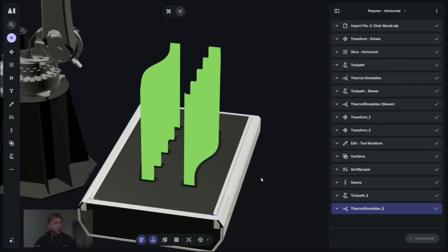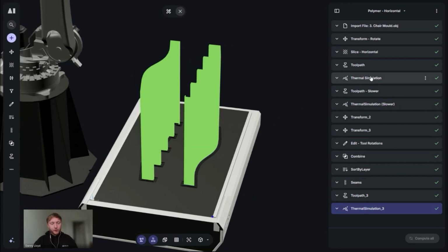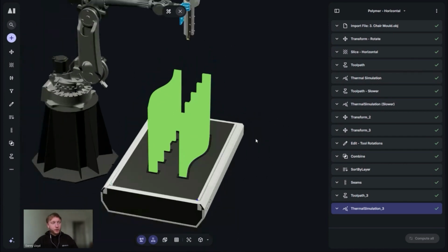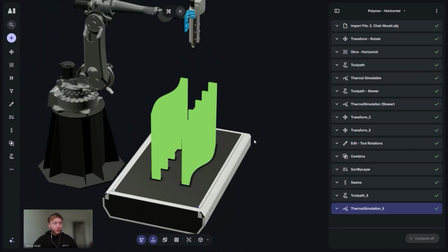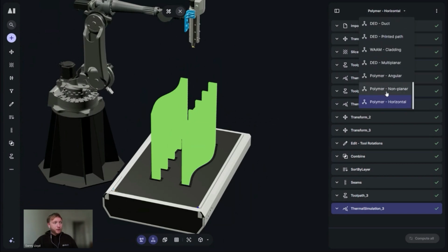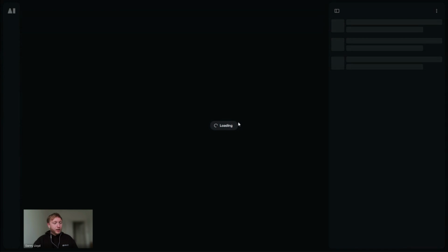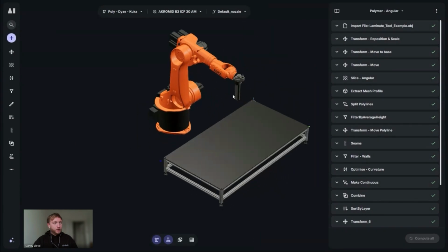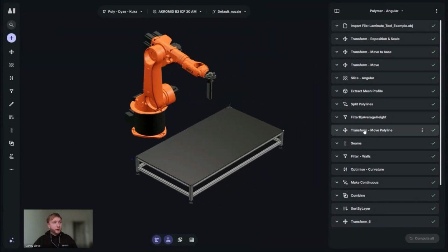Exactly. You're increasing your throughput, you're increasing your yield, and it's very easy, if you don't have this thermal simulation, to not realize that you're going to print too fast until it's too late. And then you're wasting time, wasting material. Whereas here you can really optimize, load more parts, and find a good combination of settings that will optimize your whole flow. And here the speeds were changed manually, but I'm going to have a look at this example next, where the speeds are changed automatically, and that's very important in this scenario.